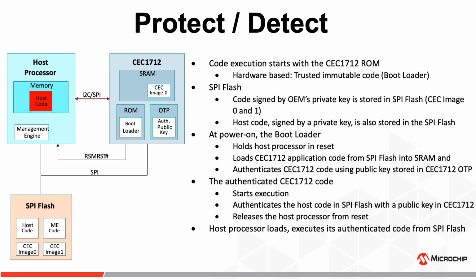We use a very similar process during firmware updates. Again, before we will allow an update to occur, we will check using the bootloader and the digitally signed signatures to ensure that the code being sent over the air has been digitally signed with the correct private key from the OEM, and that we can prove its authenticity to allow it to run.